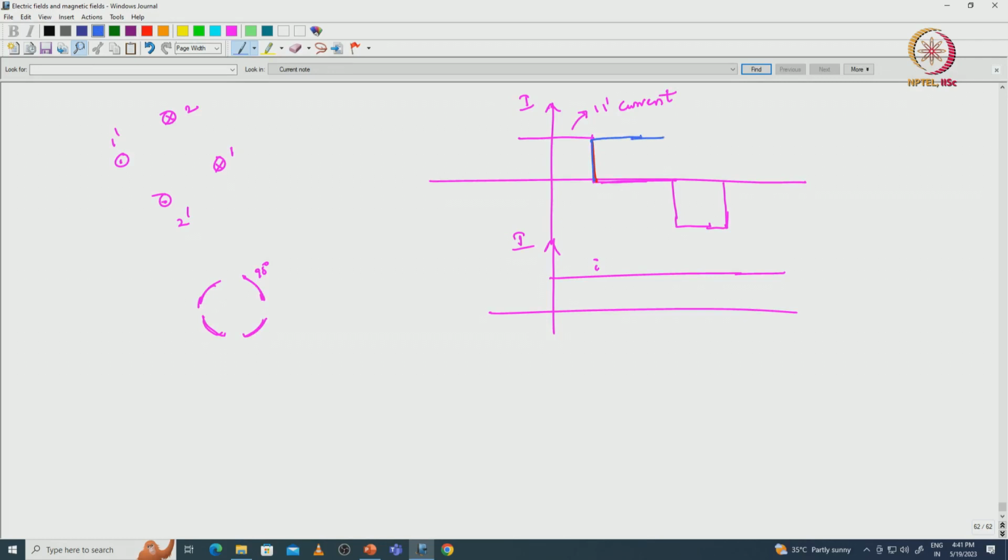From 45 to the next 45 degrees we will see this current, then it will be 0, next 45 degrees we will see this current, next 90 degrees, sorry, 45 and next 90 degrees it is 135 degrees, and then next 90 degrees we will see the 1 dash current, and after that this is a 90 degree duration. Here the A phase current will be there.